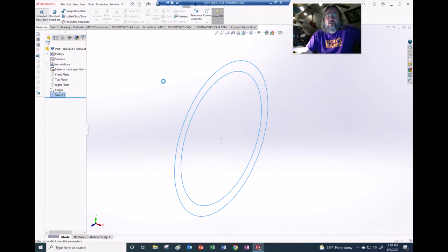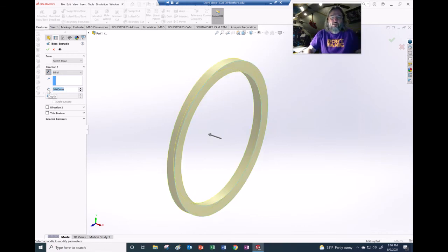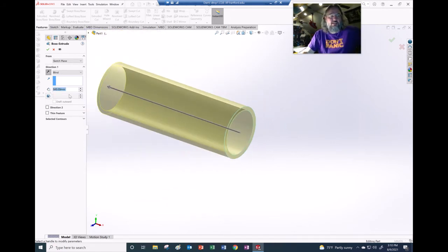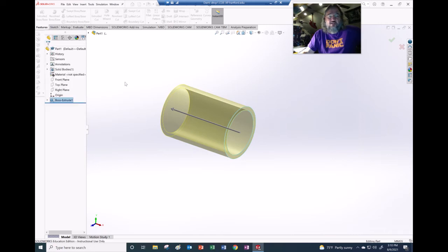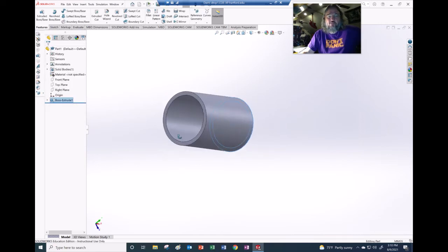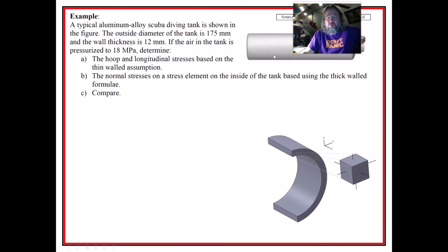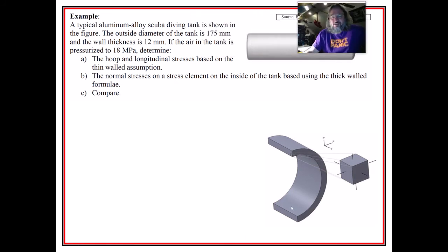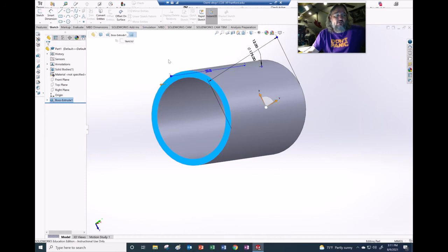For this particular thing, I'm going to model not the whole thing, but half of the piece. Let's make it 500 millimeters long. Is that too long? Yeah, that's unnecessarily long. Let's make it 250 millimeters long. That's fine. All right, so we made a little tube here, and I'm going to put an end cap on it. The original view of the piece kind of made it look like it was, let's just say that it's flat. Let's just make it flat. It's not going to hurt anything, and it's easier to model. It'll have some weird things happening at the corners.